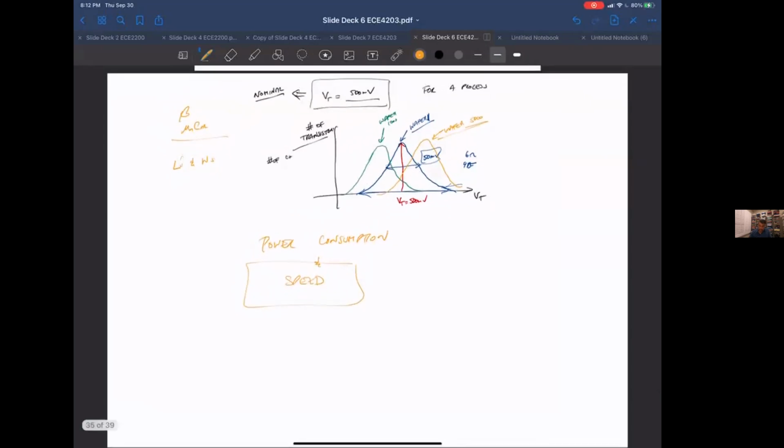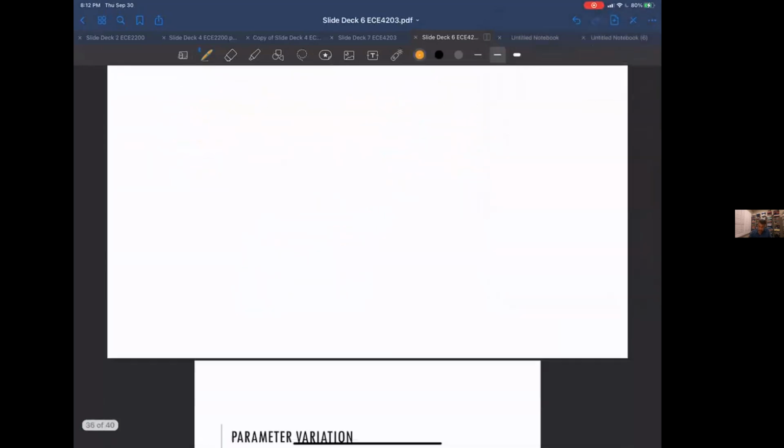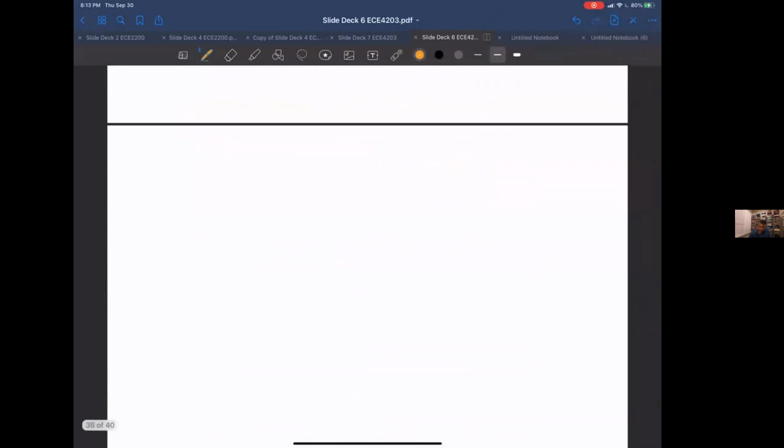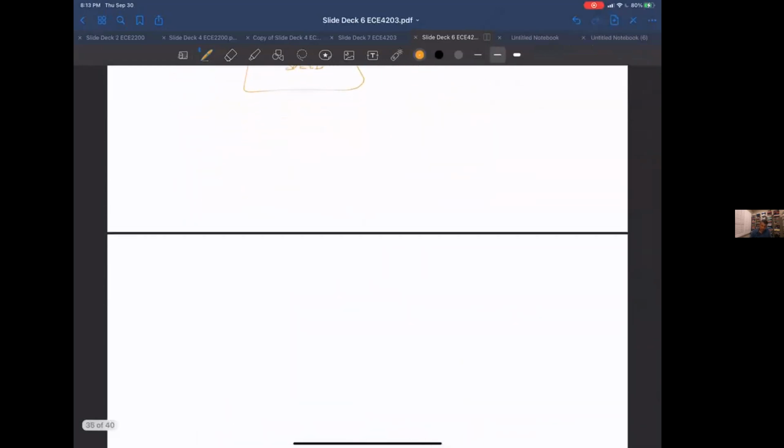So what you'll get is a bunch of different transistor values. In your SPICE stacks, or other simulation model, you'll get the typical value. Why is it called typical? It means the NMOS is typical and PMOS is typical. That's your nominal value.